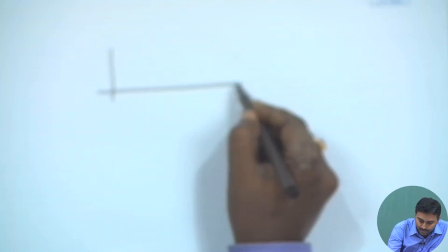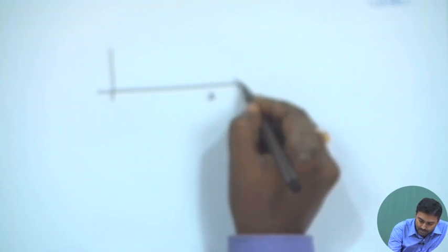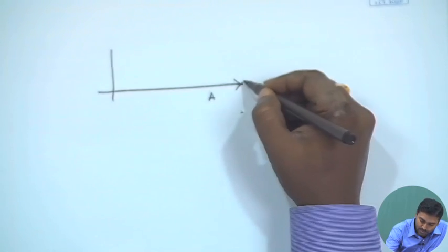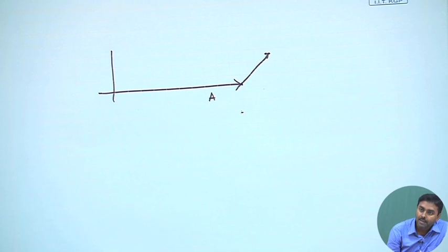Okay. So, in the last class we were discussing click noise. That is a topic we have started. We will not go into the details of it, but let me give you some basic idea of what that click noise is. Basically, we have drawn that phasor diagram, right. So, this is that AC point, on top of that the noise is being added.